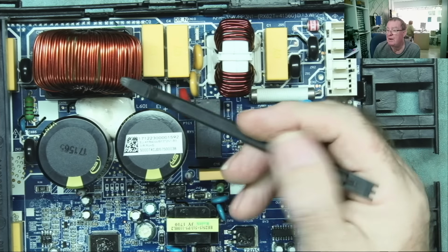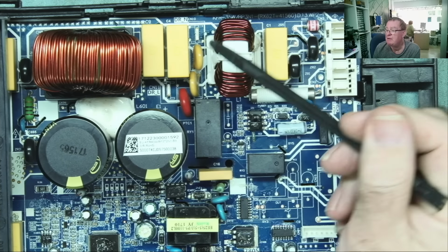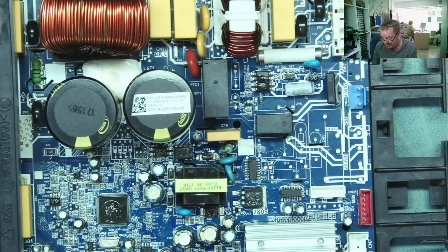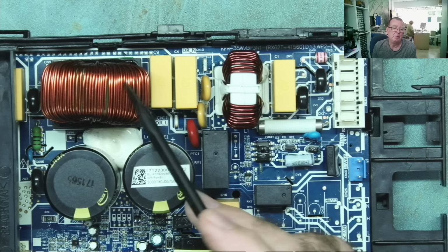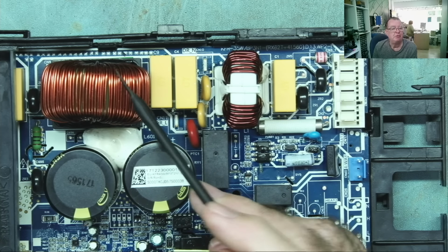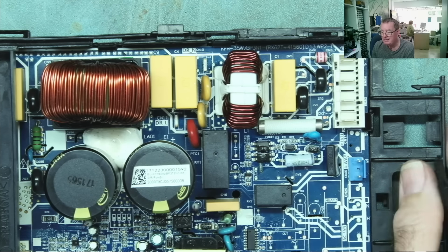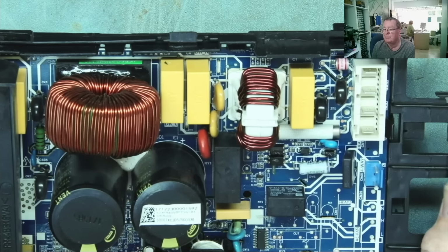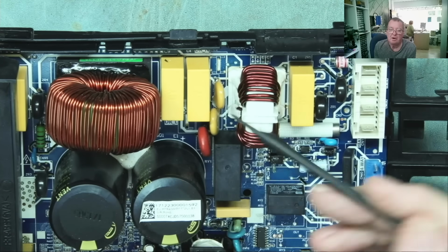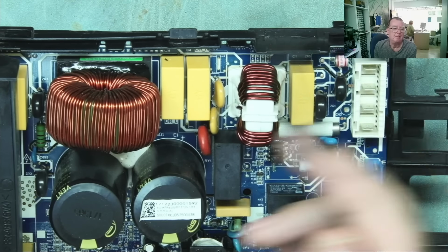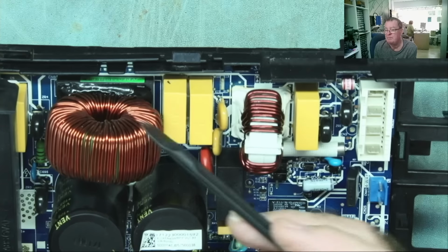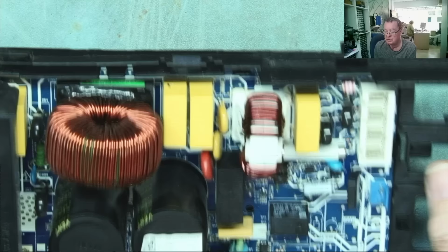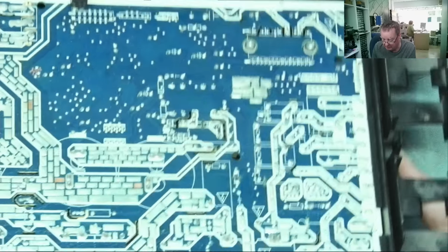So on a board like this one, we have a large inductor here, another large inductor here. We have some big capacitors, physically big. These devices are prone to not failing, but fracturing the soldered joints that connect them to the PCB. So in the case of this air conditioner board, there's a lot of vibration. The fans are spinning, for example, the compressor is running, and the vibration over time, mixed with the actual weight of the component, can cause the solder connections to fail.